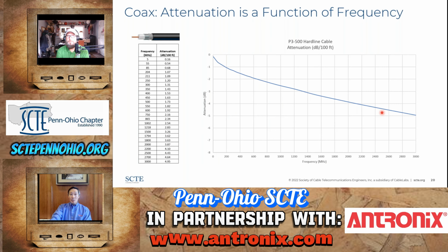And to explain the inline equalizer, we kind of need to understand the attenuation of coax. The attenuation of coax is a function of frequency. So here's a specification of a hardline coax. As you can see, the attenuation increases per 100 feet of coax between 5 megahertz on up. So this is the curve of attenuation per 100 feet.